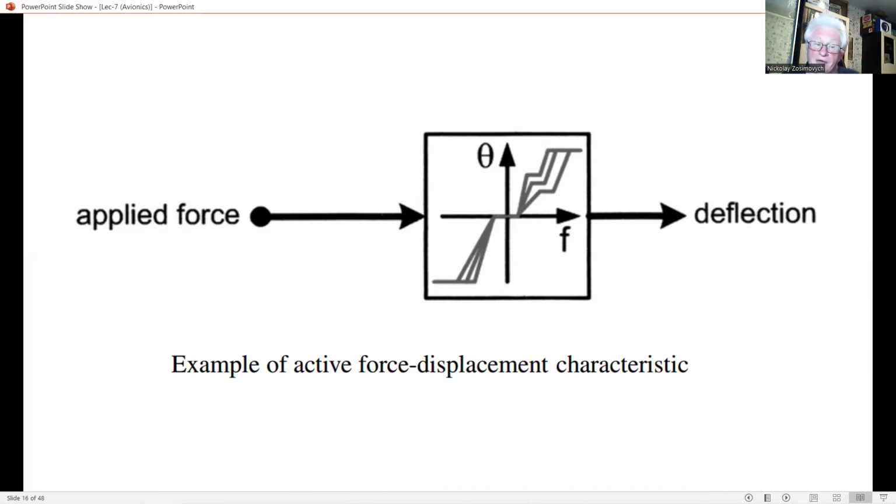With a digitally implemented controller, it is a relatively simple task to modify the force displacement characteristics of the inceptor during flight test without any mechanical changes to the unit.